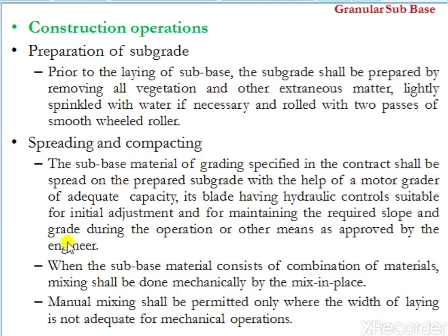We are using a combination of materials, so we will use coarse aggregate, fine aggregate, moorum, etc. When we are using a combination of materials, the mixing of these materials should be done properly, and this mixing shall be done mechanically in the site.